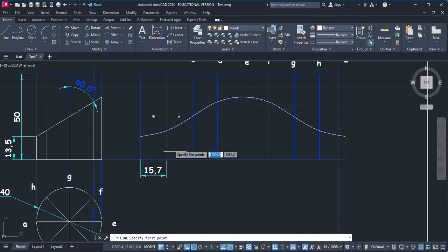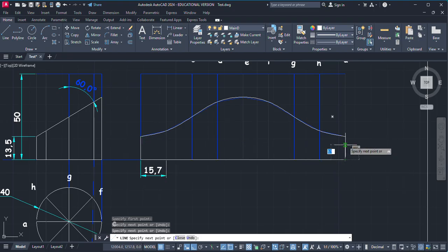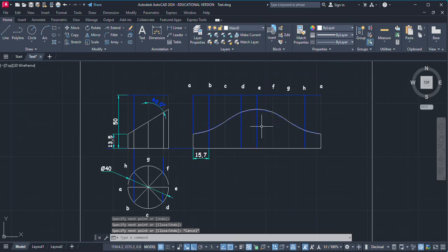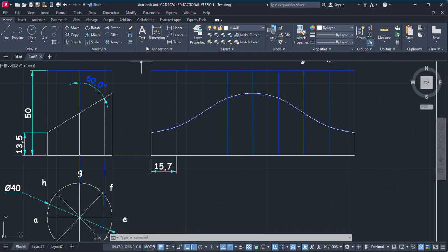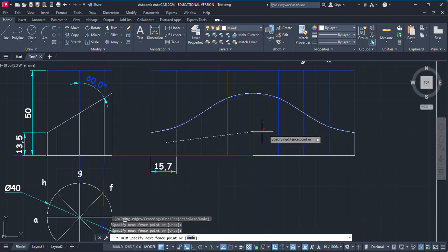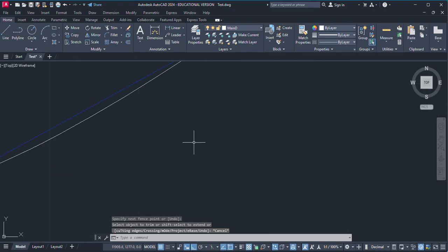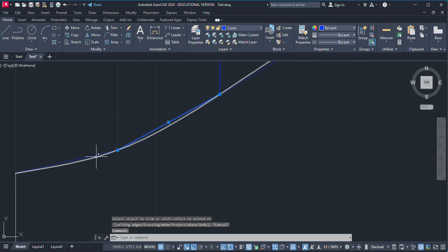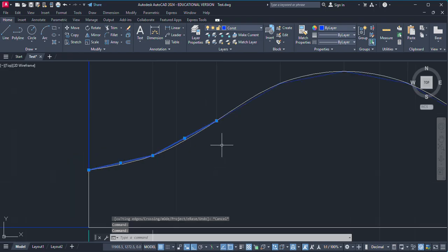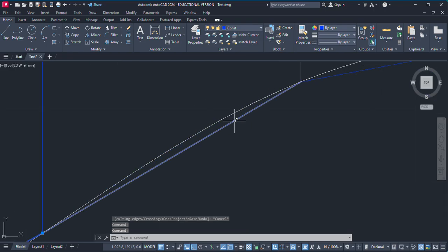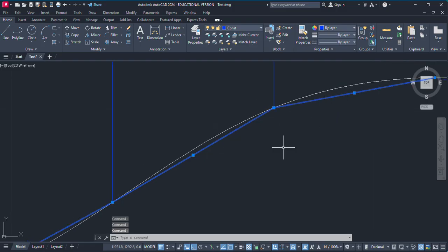Now this bottom part is a straight line, so I'm going to draw this again. Now this is the lateral surface of the truncated vertical cylinder. So this is our solution. Now just remove the construction lines from the inside portion. Select these straight lines and remove them first, then these lines need to be removed.